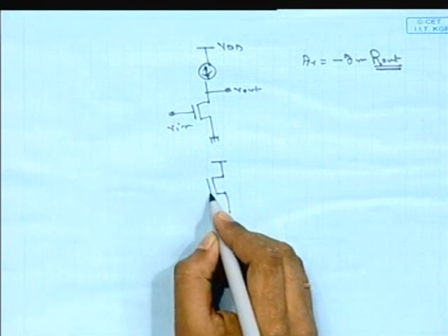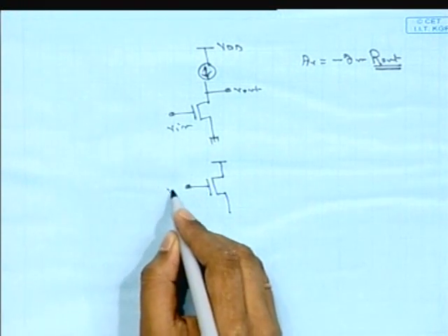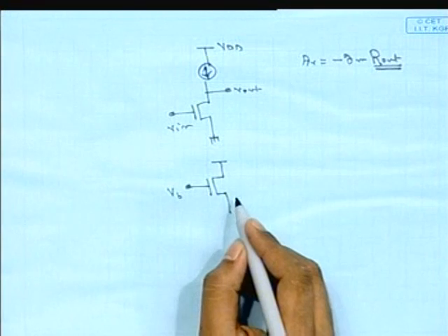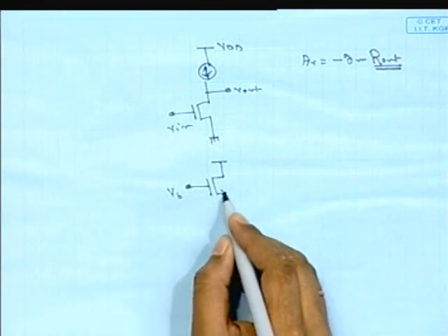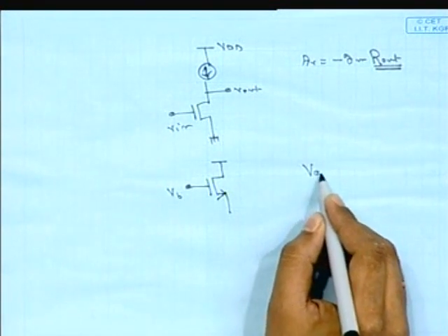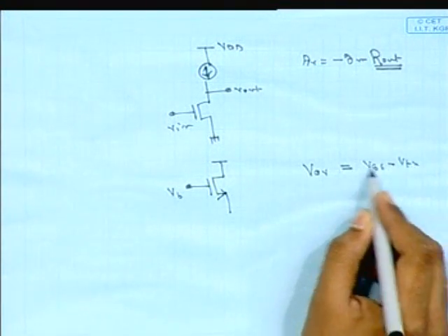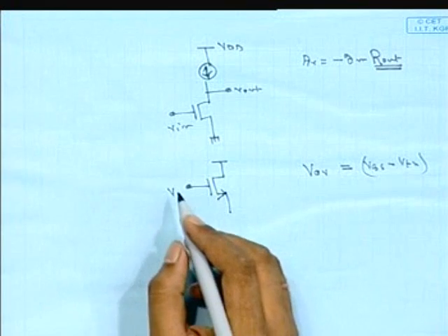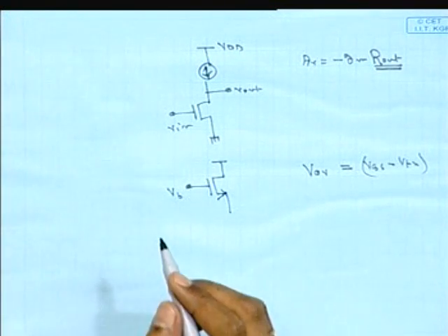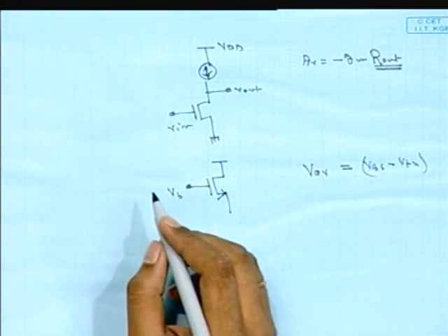But in our analog domain, that is the VLSI domain, we realize this type of current source by a MOS having a constant gate voltage. If we take the constant gate voltage, the overdrive voltage, that is VGS minus VTH, is constant. For that case, we can get a particular constant current. We are just neglecting the drain voltage for now.